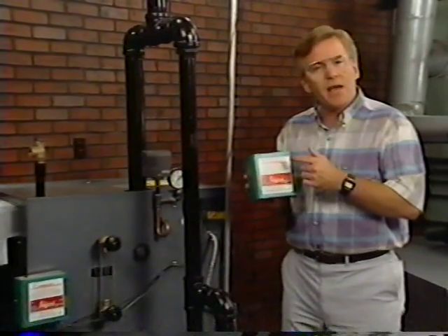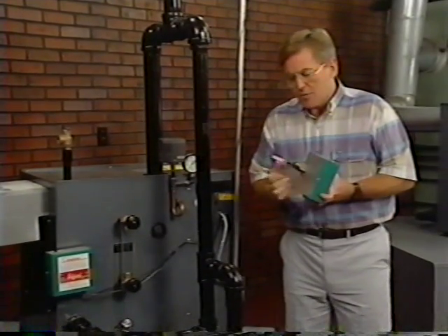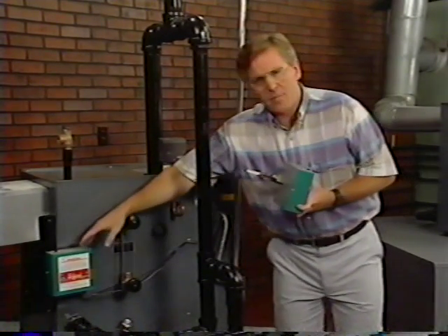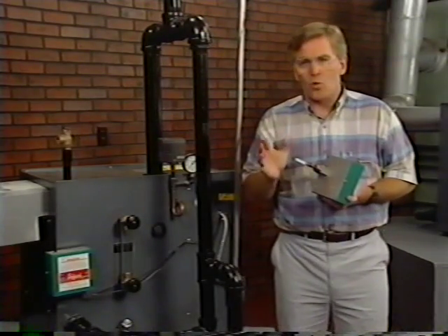One other type of low water cutoff you might come across is a probe type. Now this type of control should only be used with boilers that have a tapping provided for it. Now this probe is inserted into the boiler through a tapping. Again, it is wired to control the burner. Now, the probe completes an electrical circuit through the water to ground when it is submersed in the water. When the water level drops below safe operating level, the probe is located so it no longer touches the water. In this condition, the electrical circuit is broken, signaling the burner to shut off until the water level returns to a safe operating level.